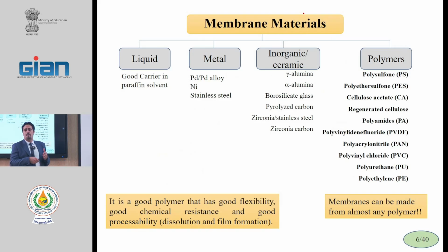And the polymers in most fabrication processes need to dissolve in solvent. We must first dissolve the polymers in good solvents and next prepare the membranes. And in most cases, the synthesized polymers have not good solubility and we cannot use them. Therefore, we must change the properties of polymers to good processability and dissolving.